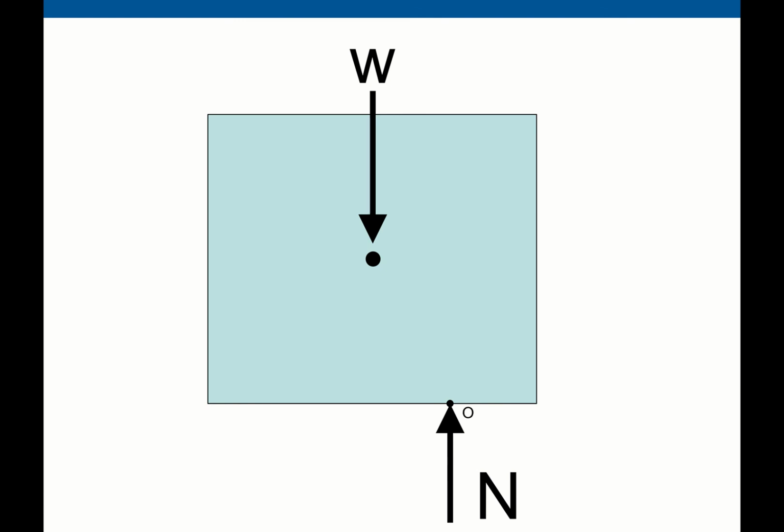And the contact point is very important. If this point is within this range, then the box is going to slip. But what if the point is very far, beyond the box width, then this box will not slip, this box will tip. Okay, we will learn this concept later, but anyway, there is a weight and the normal force. So this is the external force. We push or pull this object, then there is a frictional force.